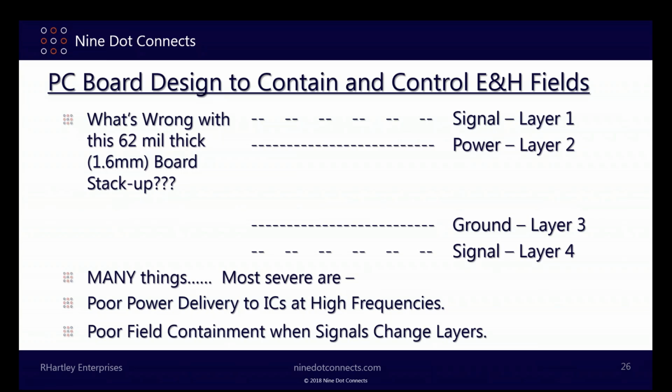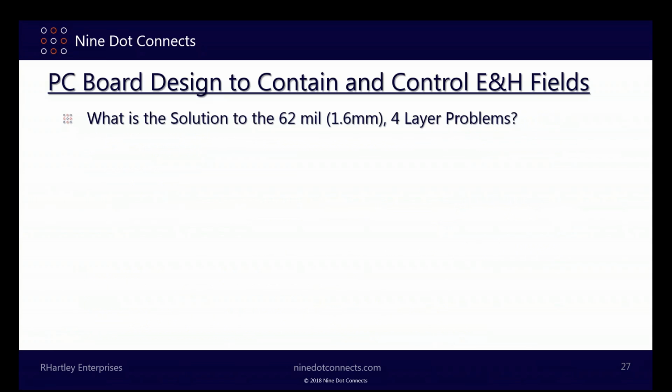If you're dealing with the kind of circuit boards that most people today have, where rise times are in the order of 300 to 700 picoseconds, this circuit board isn't going to get the job done because the decoupling caps are going to run out of gas. And once they do, there's not going to be any place with a low impedance to move those high frequency fields from one dielectric space to the other. This is a bad board stack.